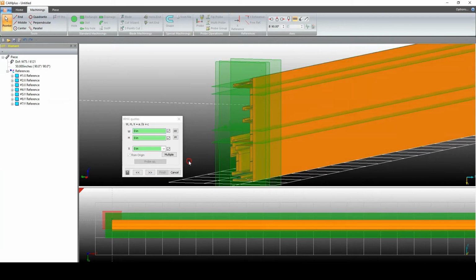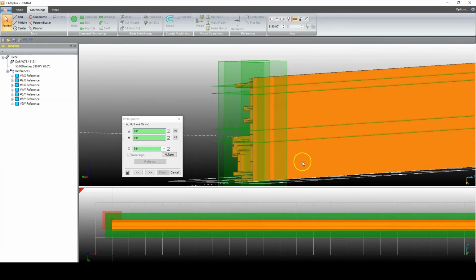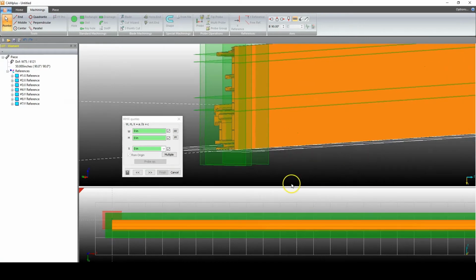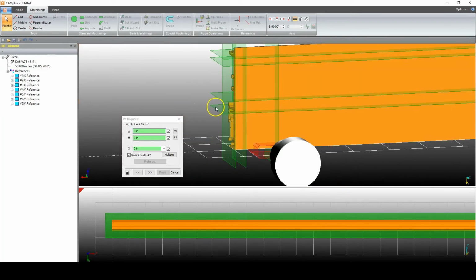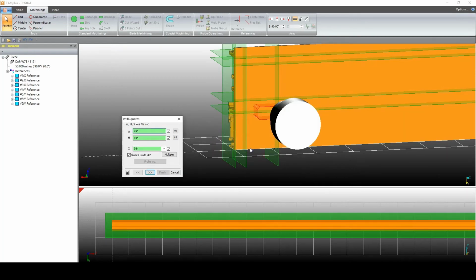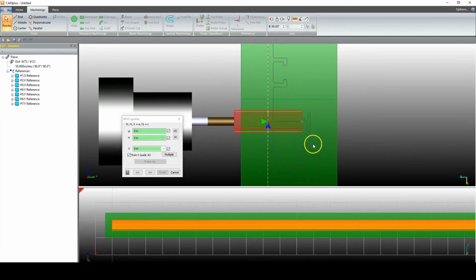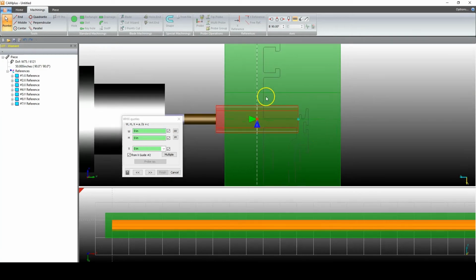And now we're going to choose which reference lines for that machining to use in order to make sure the location of it is correct. So we're going to choose this X reference line, which is the 2 3/16 line. And then the Y reference line, we're going to choose this line because it has that small tolerance built into it. Now the machining moved to the intersection of those two lines. Now we're going to look at it from the front, and we see that this machining needs to land between this reference line and this reference line. So we need to change our H.